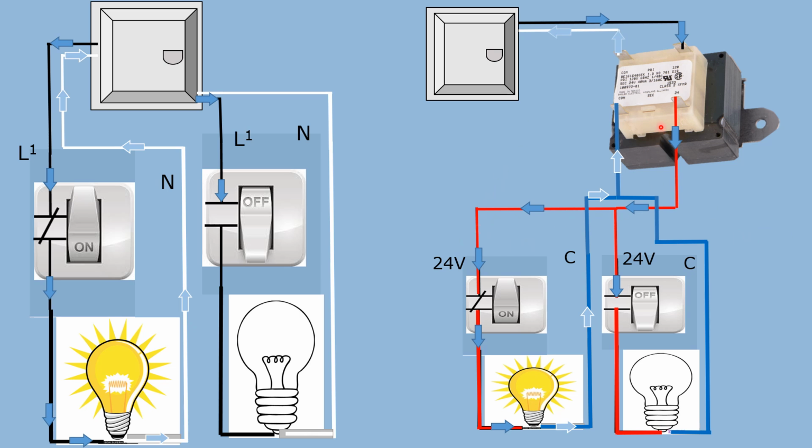And as we see here, we've got power coming out on the 24 volts, comes down, crosses the switch, light bulb's on, and back to the source. And the same here. But the power stops again because the switch is off. So there's not a complete circuit there. Nothing's going to happen.